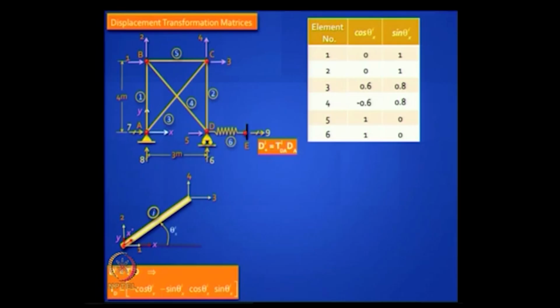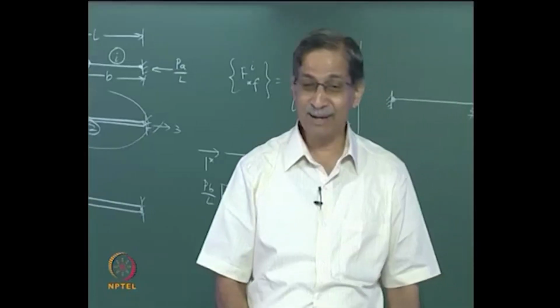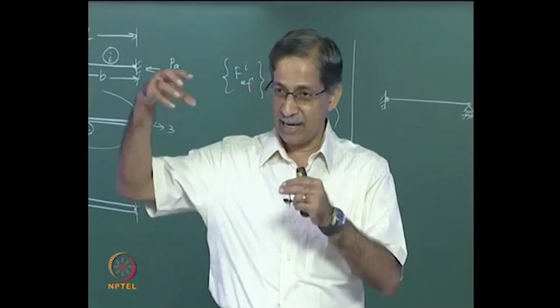You understand? I will give an example. Take element number 1. Element number 1 will have values in the first row because D1 is there, the second row, the 7th row and the 8th row. Of course 7 and 8 do not come in TDA, right. So it will fill up only in 1 and 2. What values will you put for 1 and 2? Will you put minus minus or plus plus? It depends on your angle of incidence, which is your start node, which is your end node.